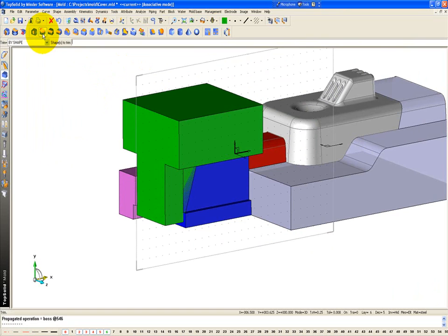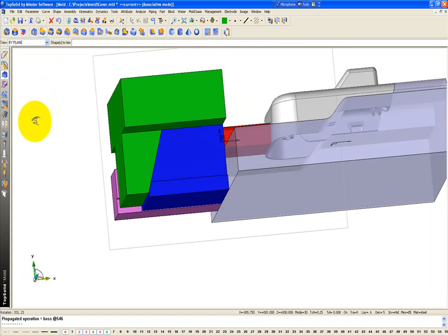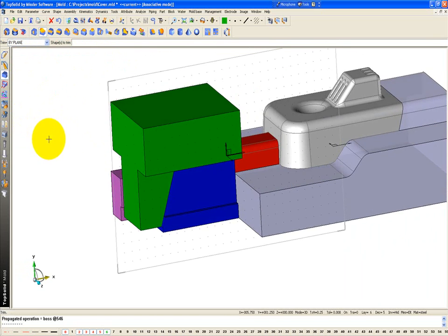Last, I'm going to go to my trim operation, trim by plane. I want to trim my slide by the planar face of my backlock, getting rid of that side. Say OK. I'm going to set Hide Tools to No so it doesn't blank out my component, and click OK. And now you can see I've passed that angle along. And of course now you could add your fillets and whatnot in there.